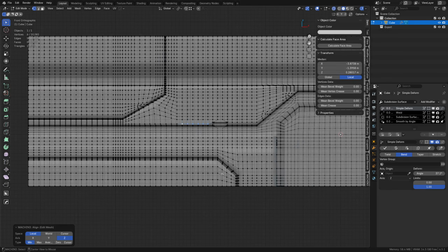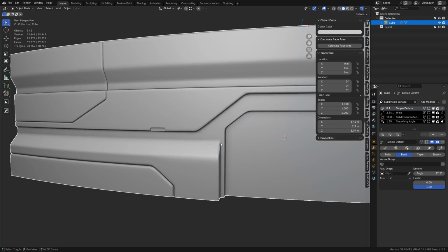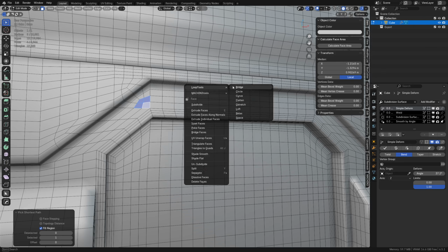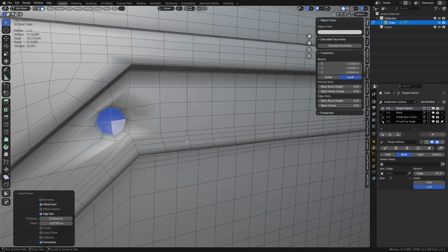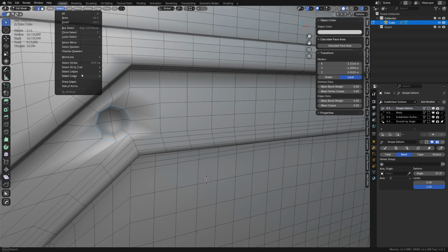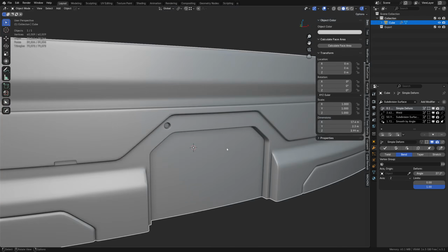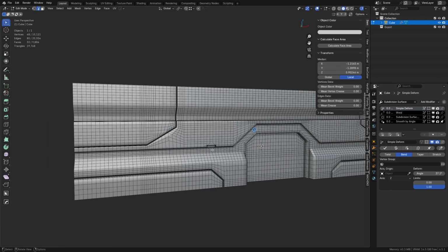Use the alignment tools with machine tools. You can cut in additional details and you can do all kinds of fun work at this point. You know, use loop tools maybe. Say, hey, you need to do that. You can maybe inset, hold control, grab this edge here, boundary select, so select loops, boundary loop, and then bevel that, right? So you can do your cylindrical pieces now, and so on and so forth.